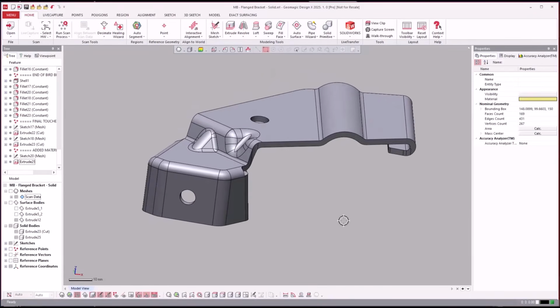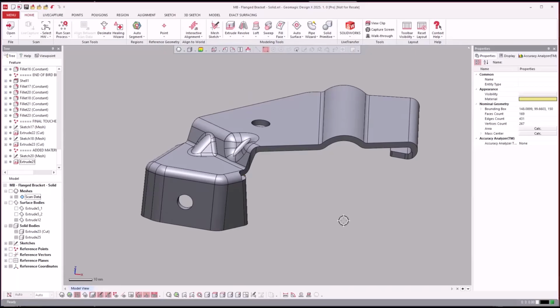So from here, you'll notice what we did is we took a slightly different approach. We modeled it as a solid body, concentrating on the top, then shelling the back away to make it a constant thickness part. The other things we learned from this is the fact that we went ahead and cut parts with reference planes. Instead of creating a lot of extra model geometry, we use reference planes to do a lot of our cutting and stuff, which is really neat. And then we use those reference planes to also trim tool bodies to then boolean away from the shape. So those are kind of three different skill sets that we see modeled within this.